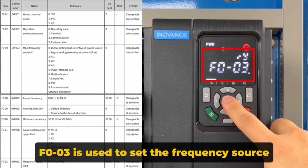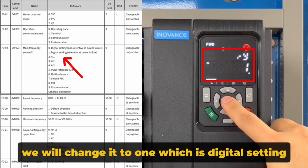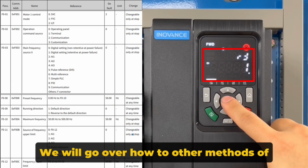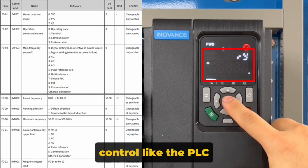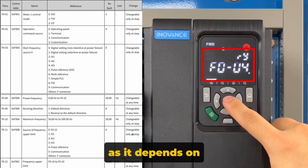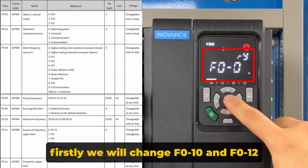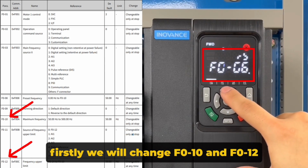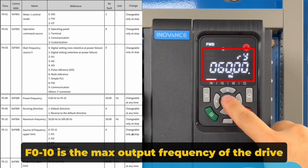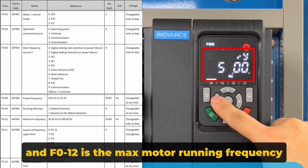F0-03 is used to set the frequency source. In this case, we will change it to 1, which is digital setting, but it retains its value upon power loss. We will go over other methods of control like the PLC or terminal blocks in future videos. The next fields are related as it depends on what speed you want your motor to run at. Firstly, we will change F0-10 and F0-12. F0-10 is the max output frequency of the drive, and F0-12 is the max motor running frequency.